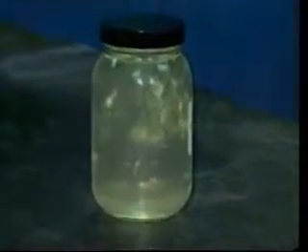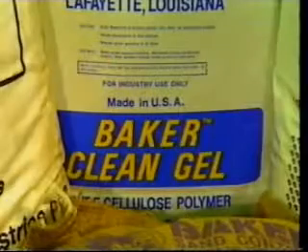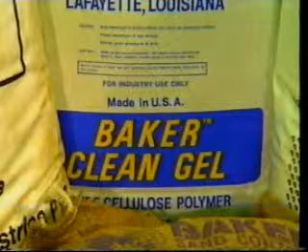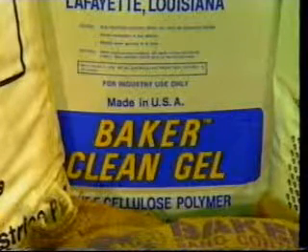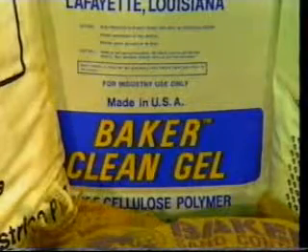The solids remaining after a gel has broken down in the formation can be very damaging. Care must be taken to use a gel with a low percentage of residual solids. A premium grade of hydroxyethyl cellulose, HEC, has been tested and shown to have only about 0.15% residual solids after the gel has broken down.